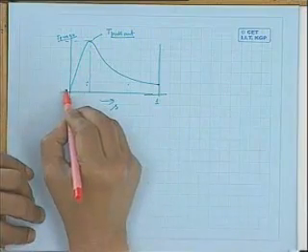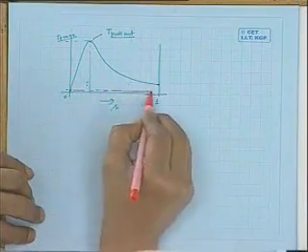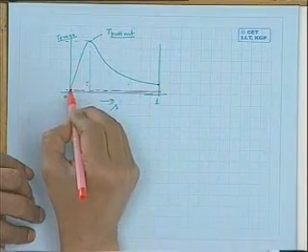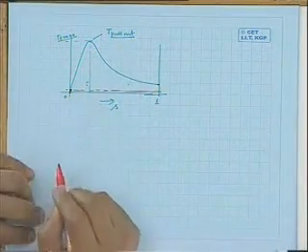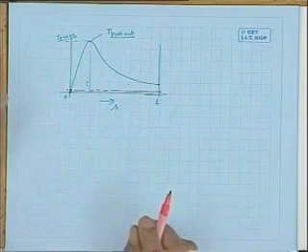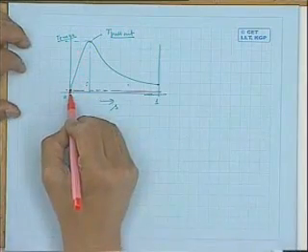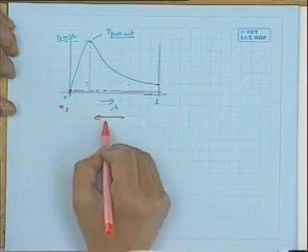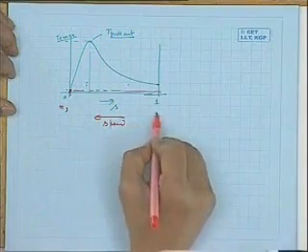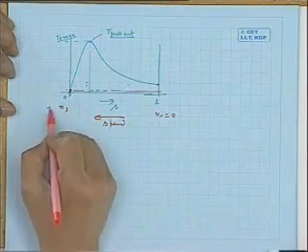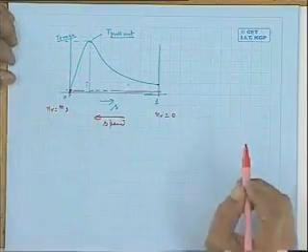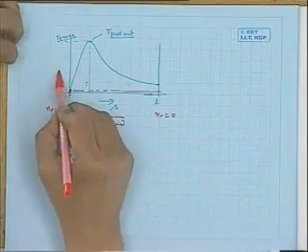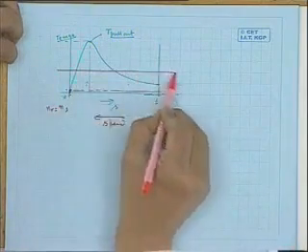When the machine is operating under no load condition, only frictional torque is present, as you can see, so perhaps the machine will be operating very close to synchronous speed. The frictional torque present on the shaft of the machine will be quite low, and it will be operating very close to the synchronous speed, ns. Speed is this way. This is nr equal to 0, this is nr equal to ns.